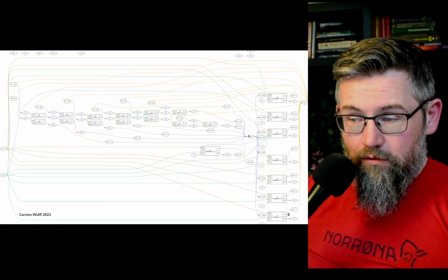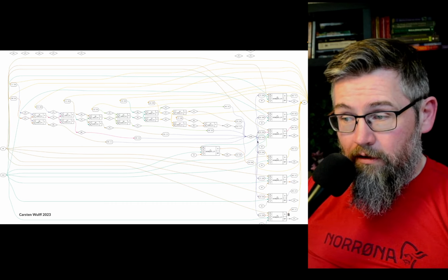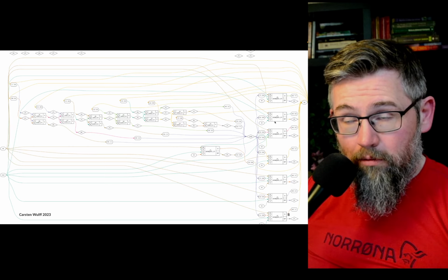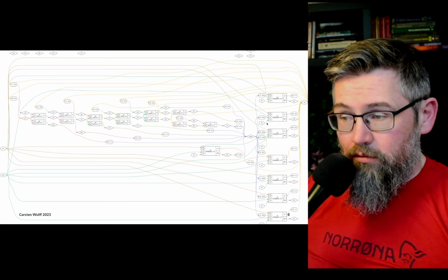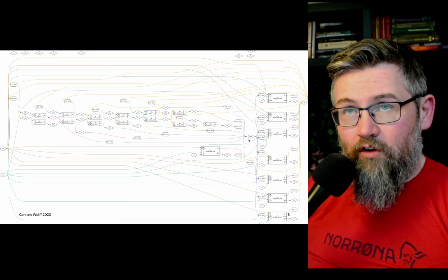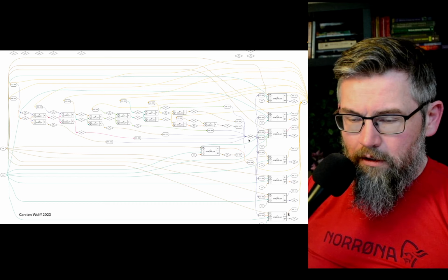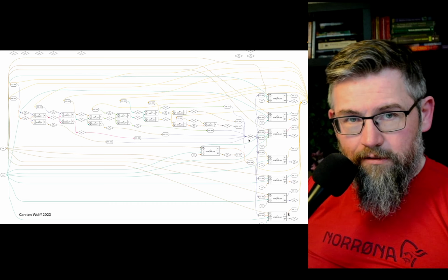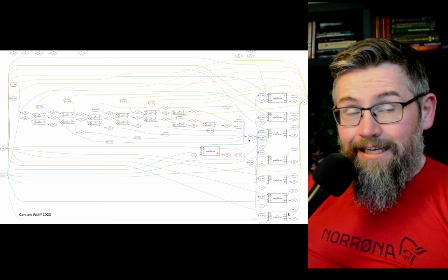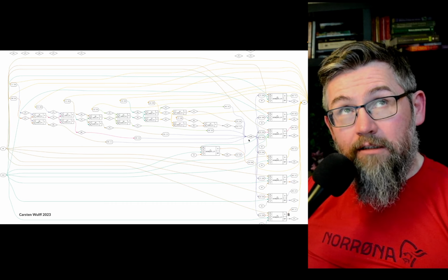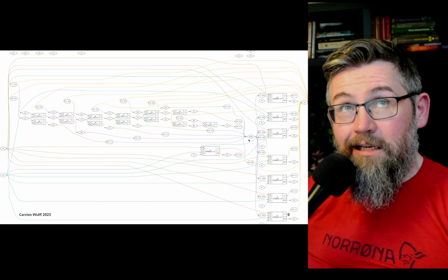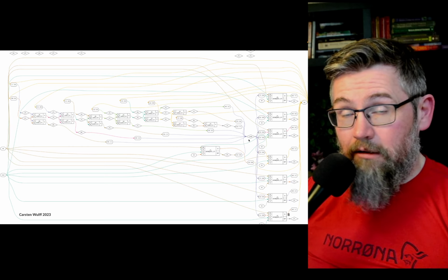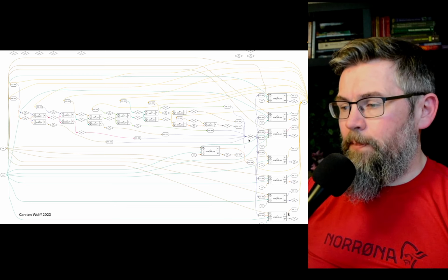And it's actually important also that the count variable is held long enough after the clock strikes, what we call the hold time, so that the D flip-flops don't change value because the data changes right at the clock, for example. But all of this is pretty quick. I mean, we can do millions, billions of gates. Maybe not billions of gates. Well, at least millions, hundreds of millions of gates on an integrated circuit. And we actually simulate that in hours, days.